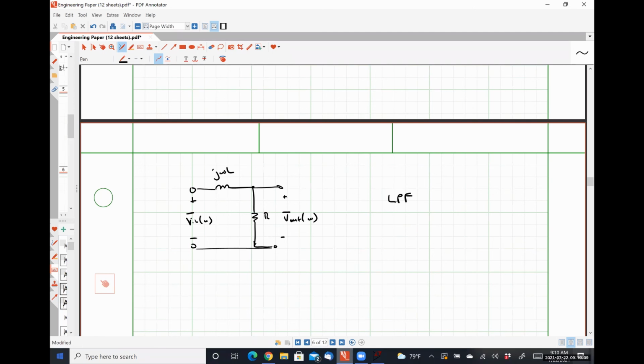So what we talked about today were the different combinations of first order practical filter circuits. So RC filter circuits and RL filter circuits. In order to get the band pass and stop band behavior, we're going to have both a capacitor and an inductor in the circuit simultaneously. Because effectively what we're doing is we're relying on the inductor to provide some portion, either the low pass or the high pass portion, and the capacitor to give us the other.